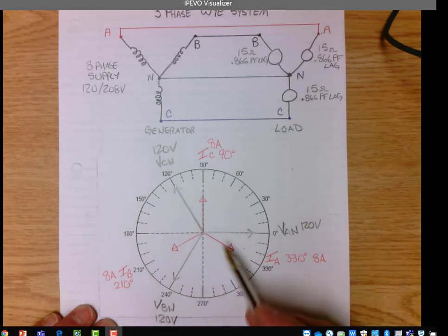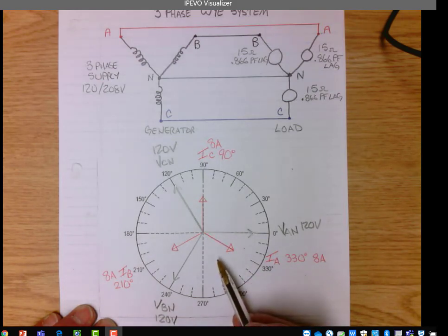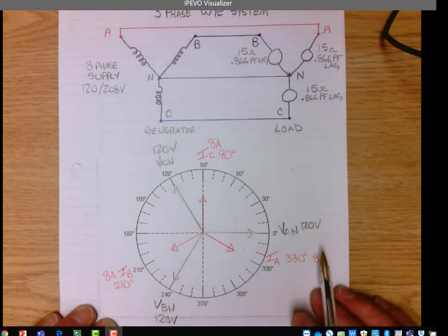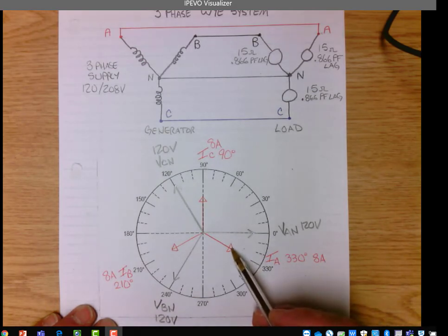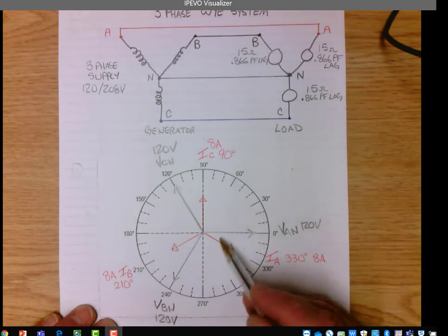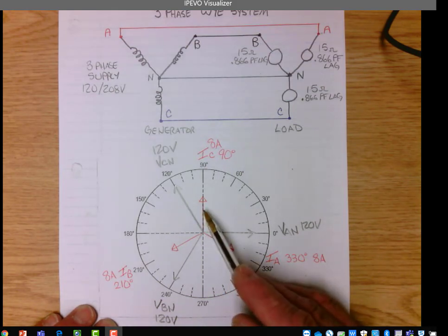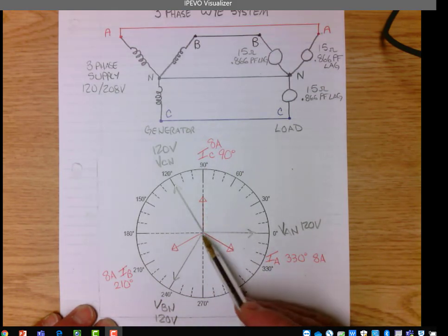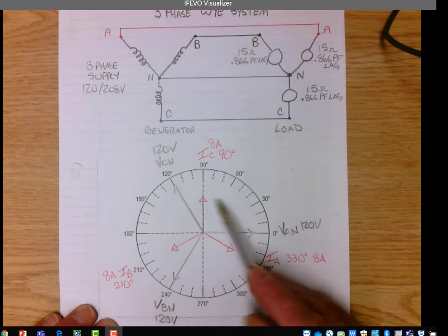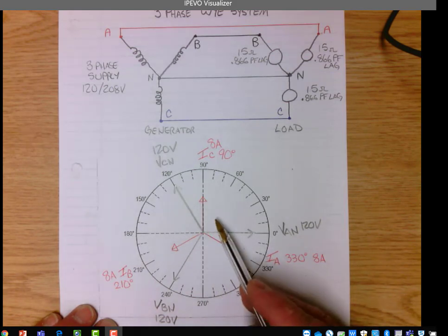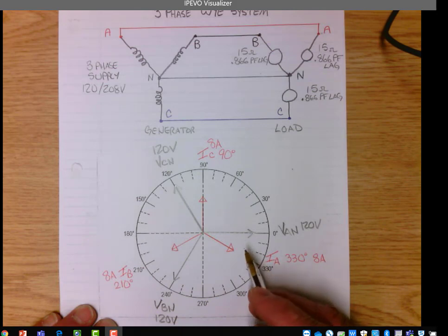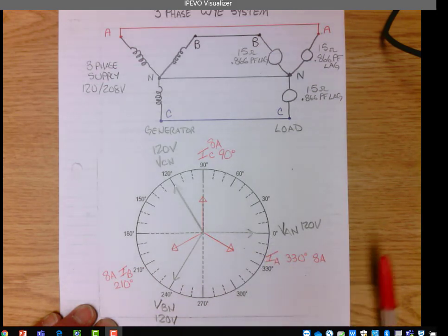The phase voltages, plot them on the phasor diagram. The phase currents, put them on the phasor diagram. And that is really all we can show for a balanced load. In an unbalanced system, the phase current is not the same in each phase, or the phase power factor is not the same in each phase. And as soon as we have an unbalanced Y-connected load, then once we have done this same phasor diagram, there's one more calculation that we can do to find the current that the neutral carries.